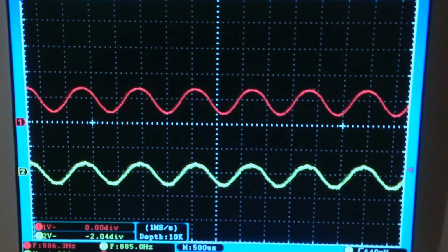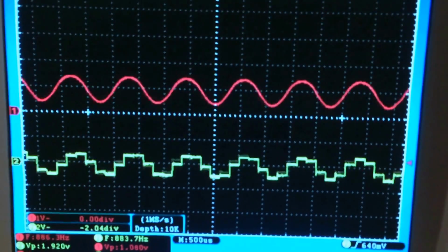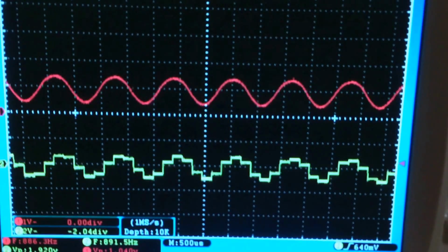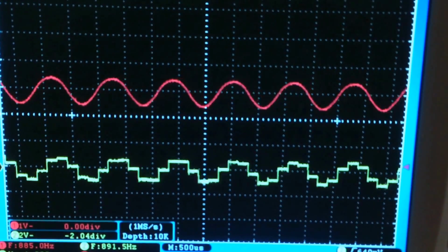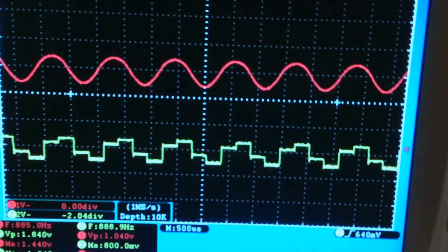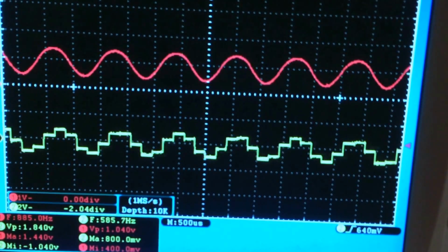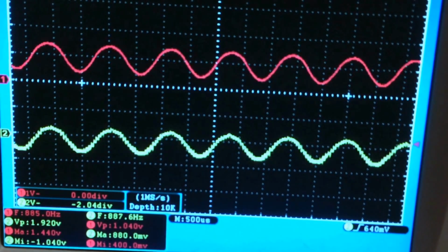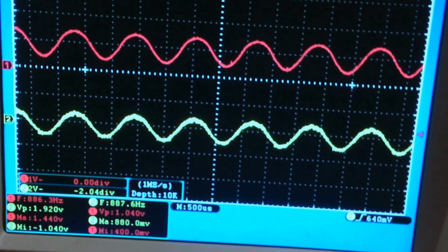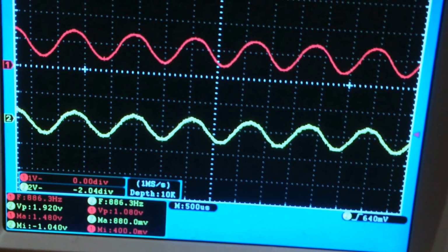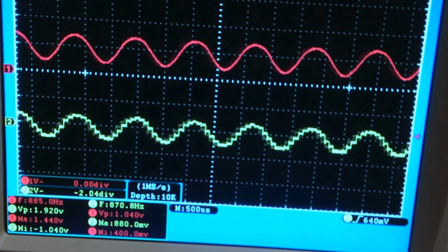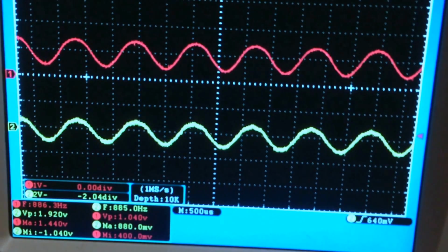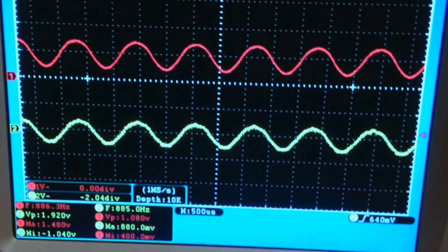Sample rate right now is at 60 kilohertz. A second ago it was at 600 kilohertz down to 6 kilohertz. This input waveform is at 900, so we're 6 times Nyquist. And so yeah, you see, works as expected. And if we put some modulation on that,